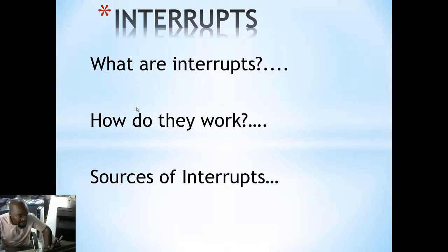Right? Should it be interrupted again while in the main function, it will leave the main function, go into the interrupt service routine, perform the function it's supposed to do, and then come back to the main program and continue where it left. It will forever do so. So that's basically how interrupts are used in the PIC microcontroller. How do they work? How do we implement interrupts in our program?